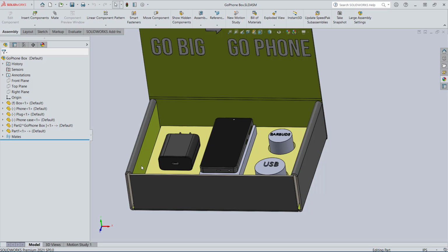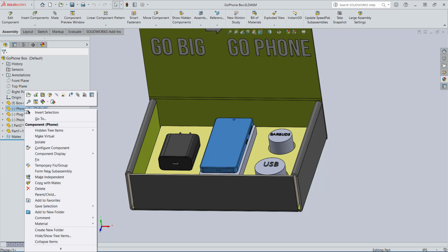So today we've looked at the workflow for creating virtual parts, and then if you decide you want a completely independent part, how to save it externally so that it doesn't have those links anymore. The converse is true as well. You can bring in a part via that normal method, and if you right click on it, there's actually the option to make virtual. So you can turn a normal part into a virtual part. I've never seen a use case for that, but the option is there if you want it.